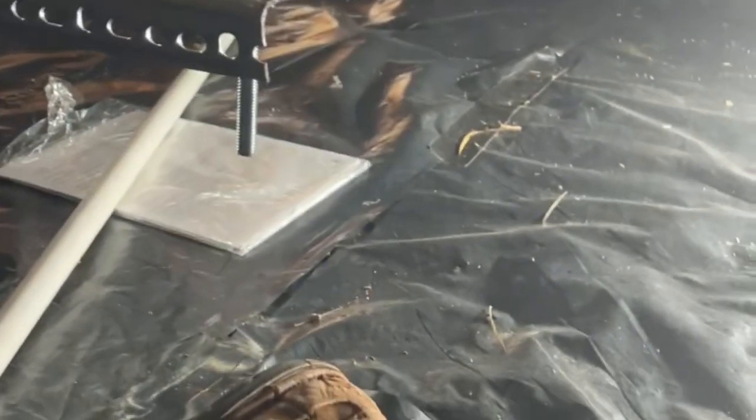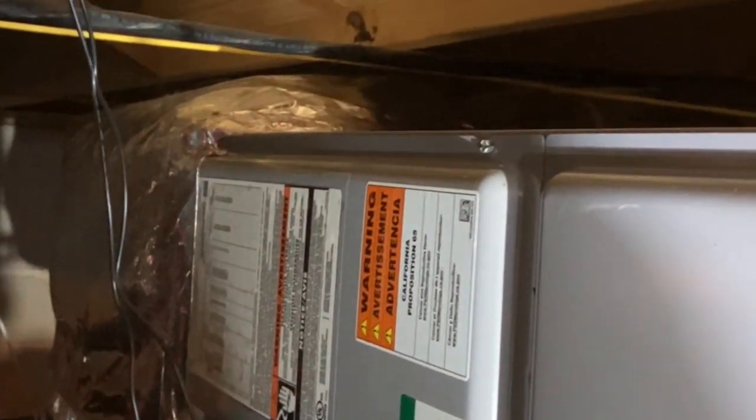So now I got to run that way and knock a hole through the wall and run the pipe on over from here. Drain comes over and comes out right there, comes from the unit and goes up right there. It has to have a trap in it to keep from sucking hot air in the summertime and keeps the drain draining right. Got the auxiliary drain pan wires ran over.